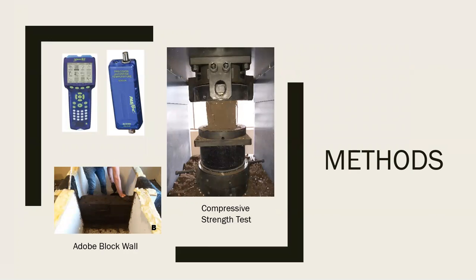With the Adobe blocks, their resistance was verified with a compressive strength test. For temperature variation and acoustic conditioning, Adobe block walls were built to be used inside a test chamber, with the blue equipment, the Spark LXI data logger, and a temperature, sound, and lighting sensor.